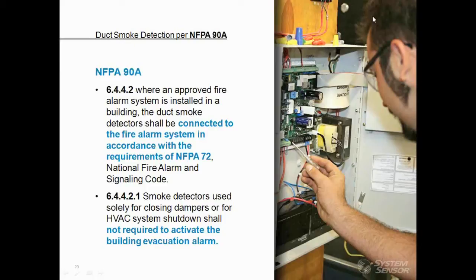The second point on this slide lets us know that activation of a duct smoke detector is not required to activate a building, that the detectors are only used to shut down the equipment or to close the dampers.